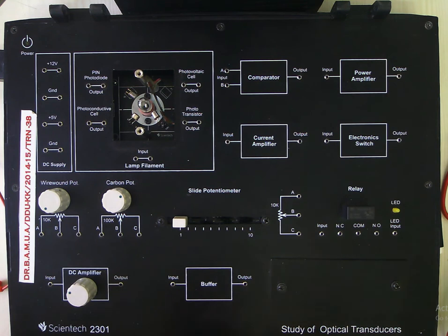And in order to actuate some further load or relay or a lamp, you have to connect that load in between the signal pin and ground or in between the supply and the signal pin, depending on whether the sensor is of PNP type or NPN type.